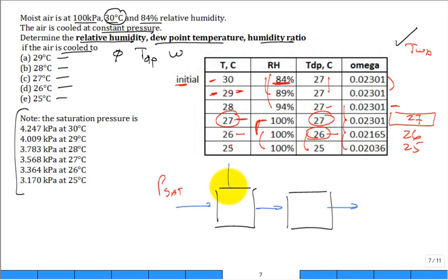So what they did was they took it in and put it in a heater section, heated it up. And so what happens when it gets really hot? What changes? Phi went down, relative humidity went way down. See? We dehumidified it. We heated it up, and the relative humidity went way down. And then they said, well, it's in the middle of August. I need to now introduce this nice dry air into the room. I need to cool it. Okay, fine. So they put another coil right here with cold water, and they chilled it or cooled it. So the temperature dropped back down.